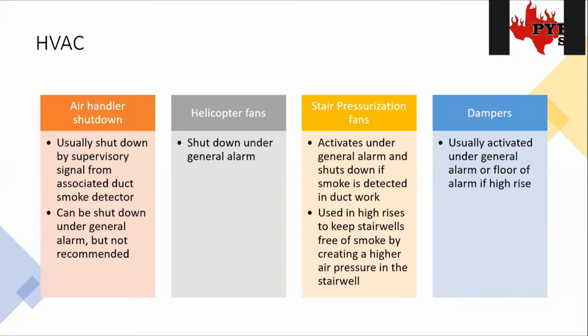Then there's stair pressurization fans. These are another thing that's typically only seen in high rises. You might see them in a mid-rise or something. I'm not sure. I know for a fact they're in high rises. The point of them is they pressurize the stairwells with extra air, so that whenever smoke is spreading on a floor, it's going to hit that higher air pressure in the stairwell, and that higher air pressure is going to push the smoke back away. That way, as people are evacuating in the stairwell to safety, they're not going to get choked up by smoke, or their vision's not going to get impeded by smoke, anything like that. Instead, it's going to be forcing all this fresh air into the stairwell.